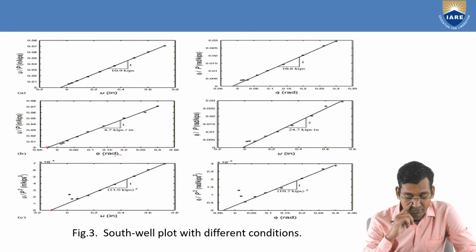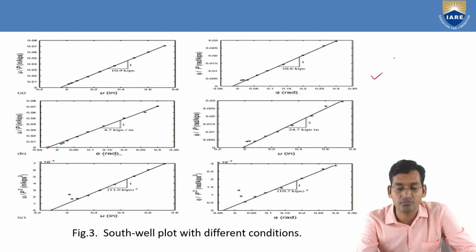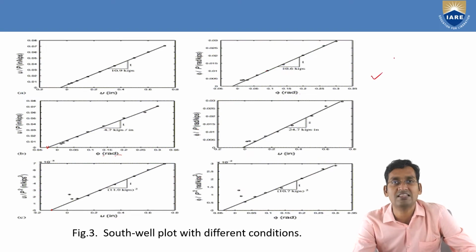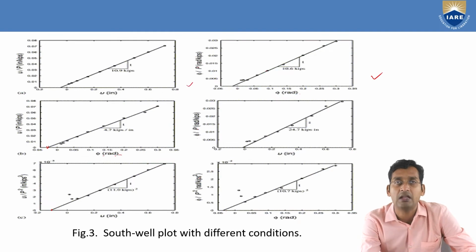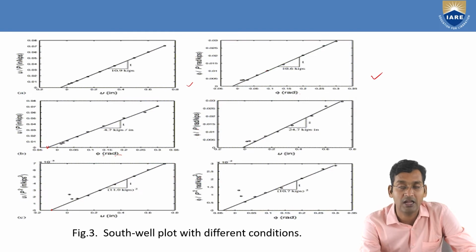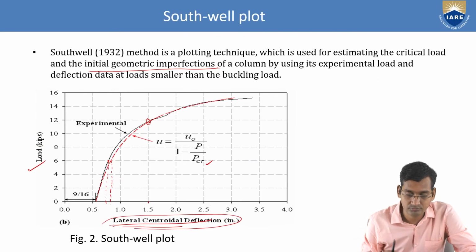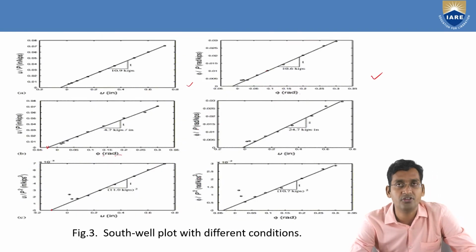So whatever the different conditions of the plot are, with deflection, whatever the type is, the distance or deflection in anything by applying the load, we can plot the curve, and according to that we can find for that particular deflection that term, imperfection. So imperfection versus load, that is called the Southwell plot.